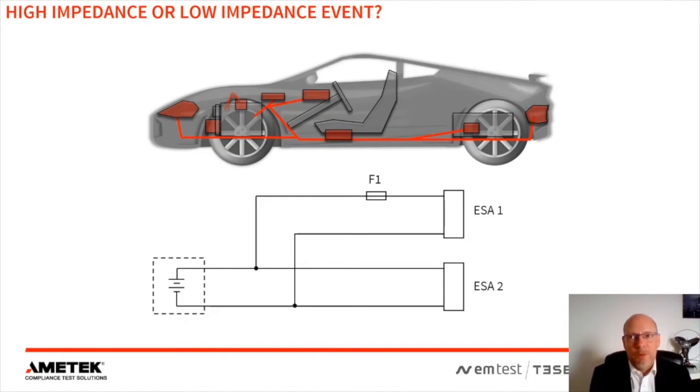For example, an open circuit event would be a loose or bouncing contact, something like that. So the DUT would see an open circuit back to the rest of the vehicle. And that's one of the things we're going to talk about today. It makes a difference to how the DUT behaves, how the test equipment should be, and it has a large effect on just everything about the test.